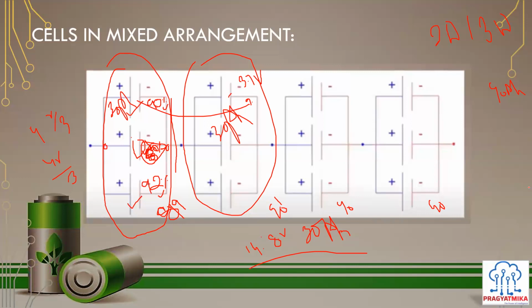So at the time of charging, you have fed the value up to 90%, but during the balancing process that 1% is discharged and has not been utilized, and the range of your pack will also be lesser. That is being driven by the lower module value, and the excess charge or excess time you have taken for charging the battery pack has gone wasted.